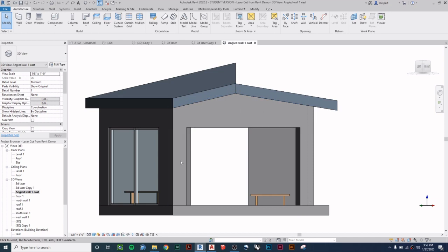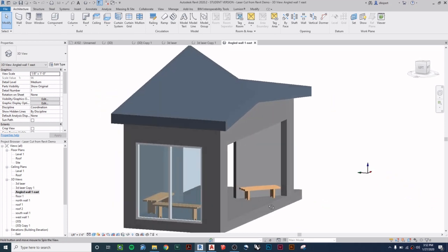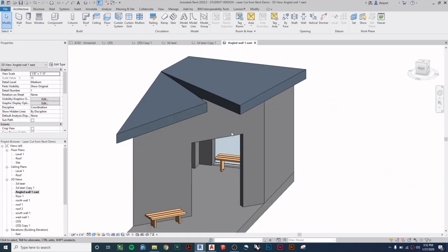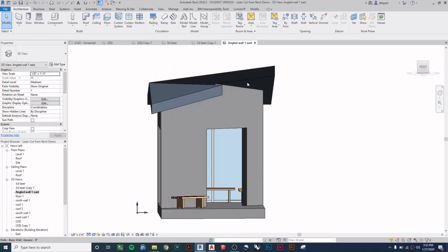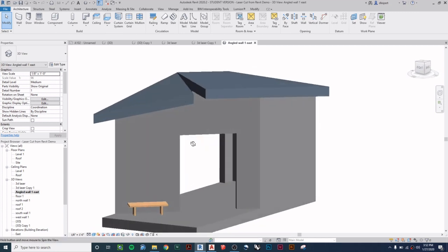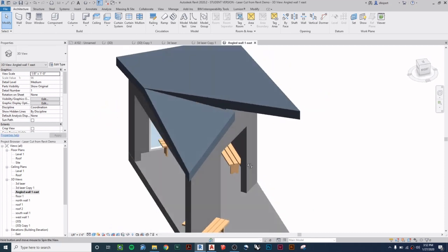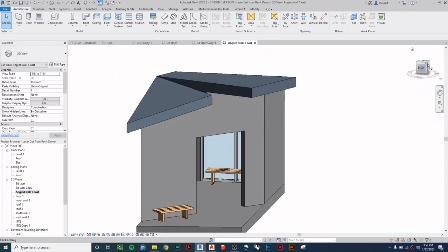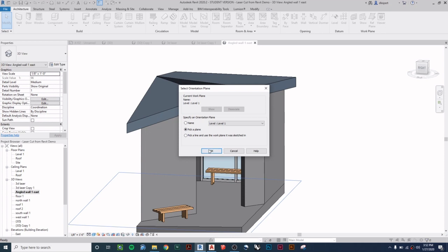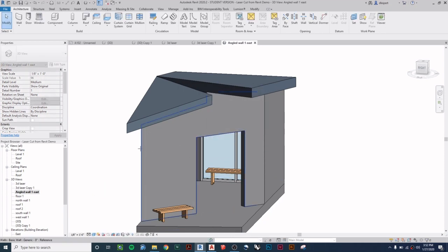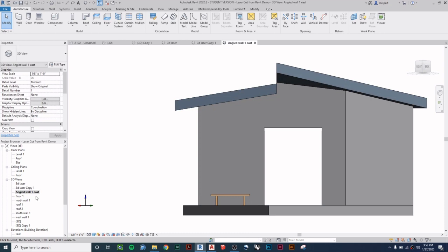Now I know that this is the exact size of the wall that I want. If I was looking at it on an angle like this, or like this, I'm sorry, I clicked on the wrong wall. If I was looking at it like this, it would not be the right size. When it goes to cut out the boundary for this wall, you'll see that it's on an angle. So I need to look at it orthographically, or straight on, perpendicular to the surface. So to do that, once again, right-click on the view cube, orient to a plane, and then pick a plane, say OK, and then make sure you hover on the edge of what you want, pick that plane. And so this is the right one. So this is my angled one wall, and then it's towards the east side.